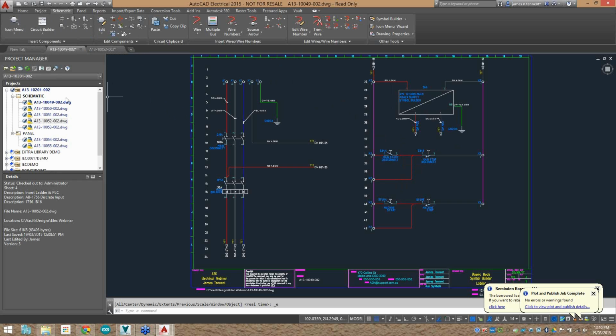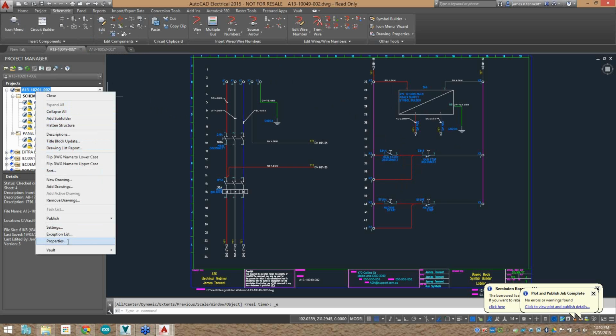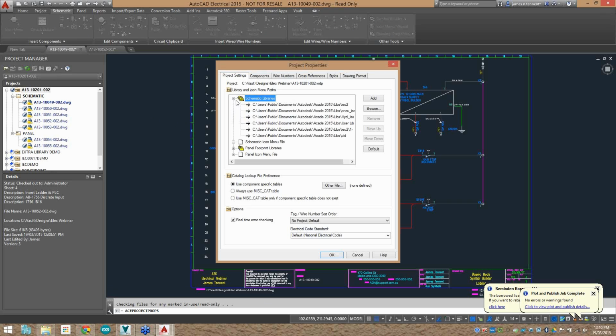So when we set up AutoCAD Electrical, we would set it up with a specific library that we'd want to use. In my case, I'm using the IEC library, and you can see it just by the end of the file path there. You can see IEC2. Now what that actually means is we're using the IEC library, and the text that will be inserted near the symbols, and you can see an example of the symbols just near that ground symbol there, is 2 millimeter high, and that's what the 2 is indicating.